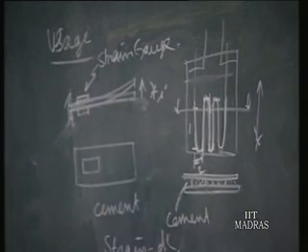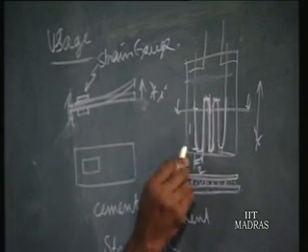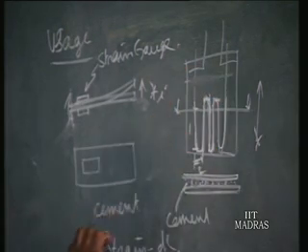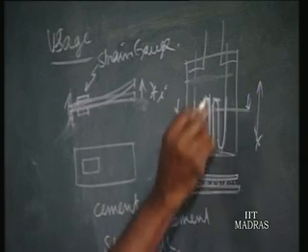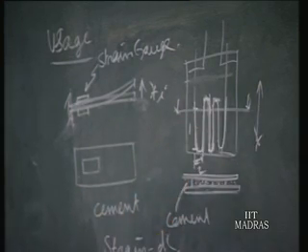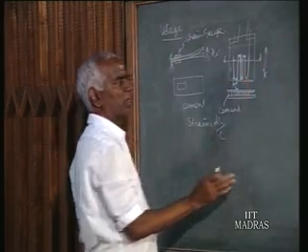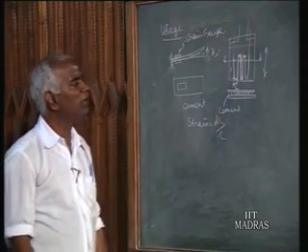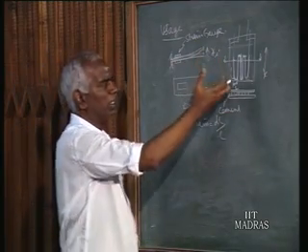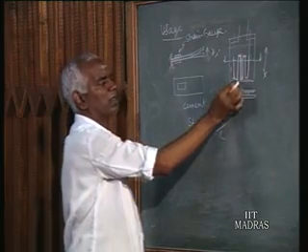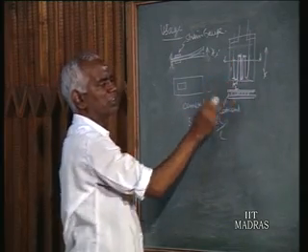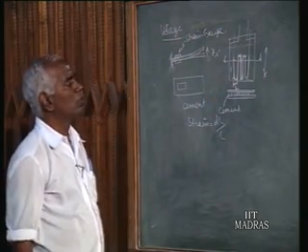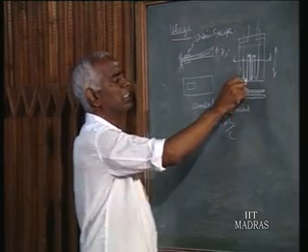So for a given strain in the axial direction, you have similar segments, 6 segments in the axial direction and 5 segments in the transverse direction. So what happens for a tensile strain, the linear along the axis, the wire will extend due to tension, so resistance will increase. But for the same strain in the transverse direction, the cross section increases and you will find resistance is decreased, rho L by A.